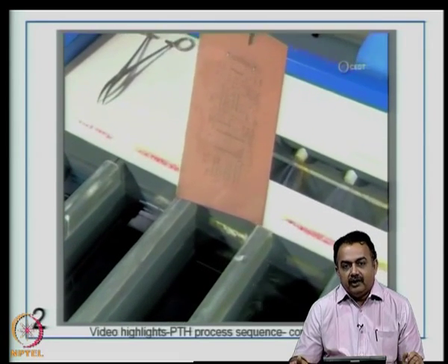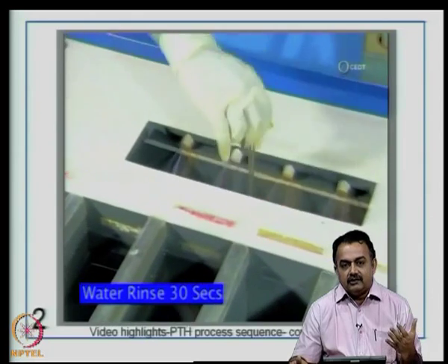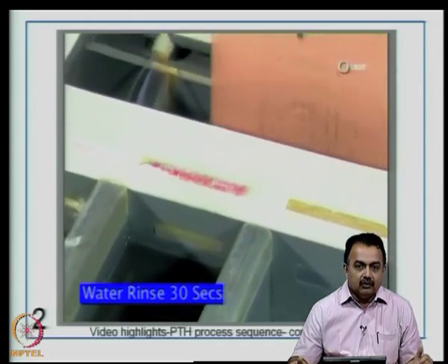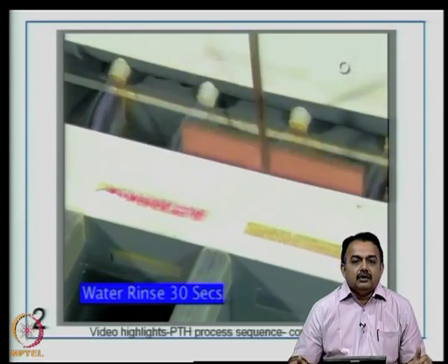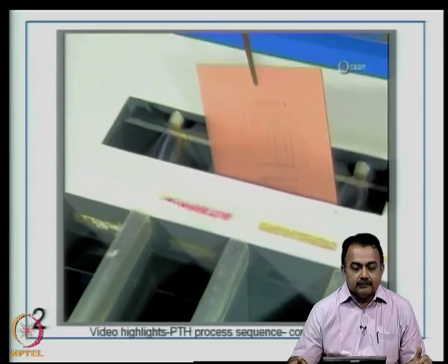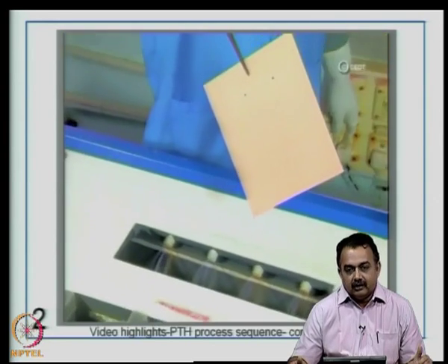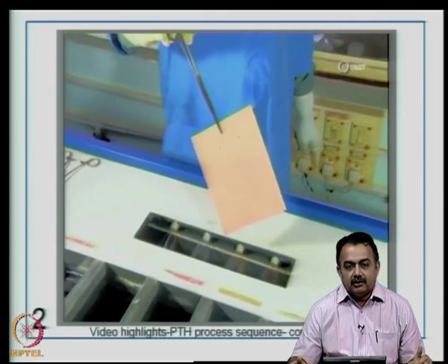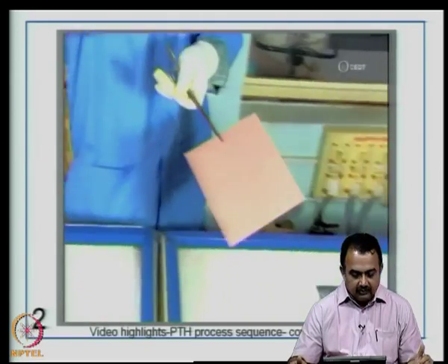Mind you, we are activating the surface as well as the through hole walls. We can't selectively do for the hole walls. So, any process here will cover the hole walls as well as the surface. That will ensure good binding and provide better connectivity from the top copper surface to the bottom copper surface.